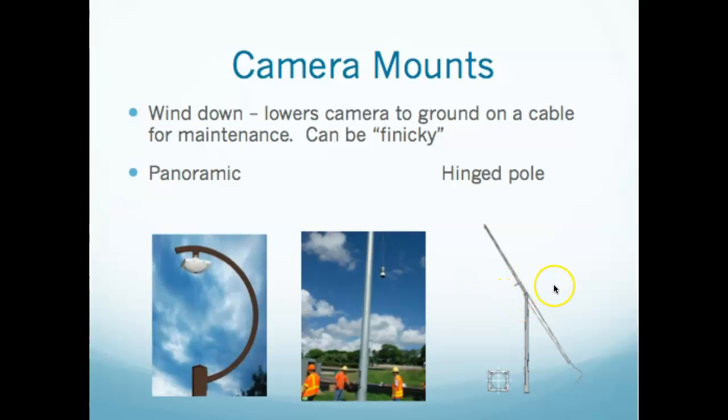But they will save your cost of ownership because, again, one of the biggest things with the cost of ownership, especially with external cameras, is the height you have to work on them. You have to get a certified lift truck, a safe way to get to that camera if it's up over 20 feet for sure. And that's going to cost you quite a bit of money. Certainly in the life of the camera, you'll spend more on maintenance than you would on the camera itself if you have to get a lift truck every time to work on them.